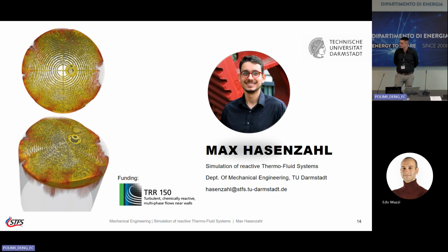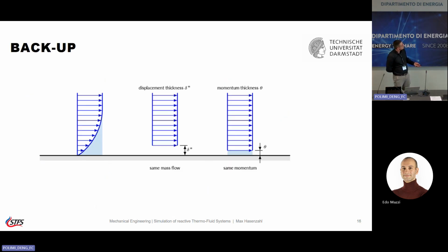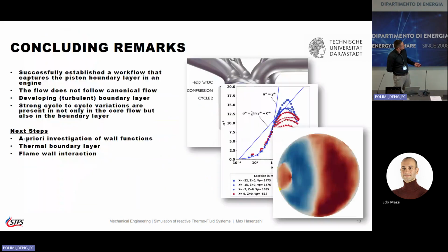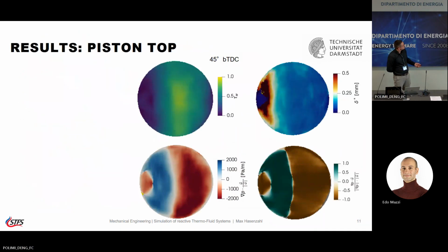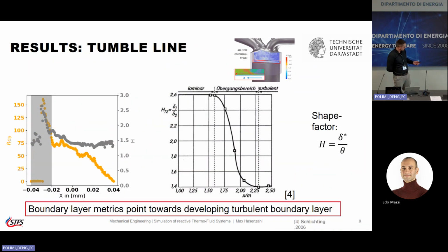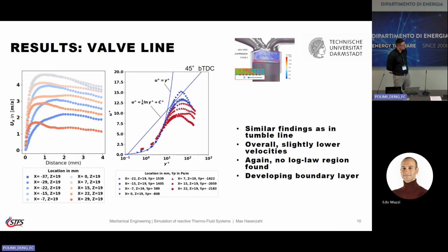And then, in my opinion, we had this idea of, well, if I understand the pressure gradient, then it might be closer to not the logarithmic, but above or below the line, which also does not work, because here this is a developing boundary layer. So you wouldn't even expect that to transfer. And then we really have to go to non-equilibrium wall functions, because this notion of having production equal dissipation in the logarithmic region just does not hold.